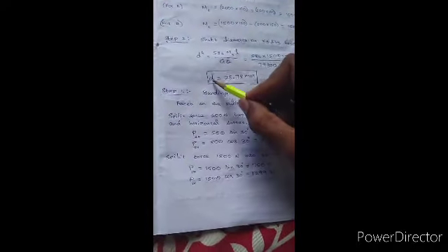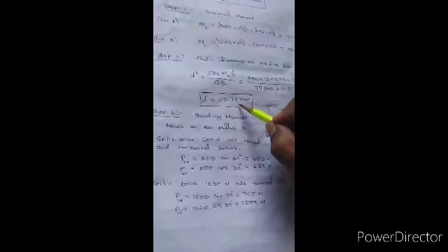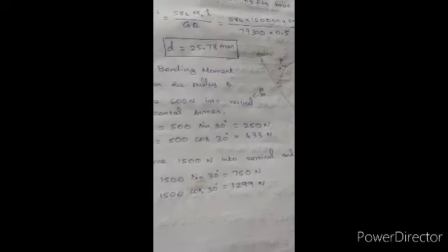Now you have to take the root. If you take the fourth root, you will get the answer as 25.78 mm. So one answer we got based on rigidity, based on the rigidity modulus: 25.78 mm. Still we have one more method, that is the ASME method.